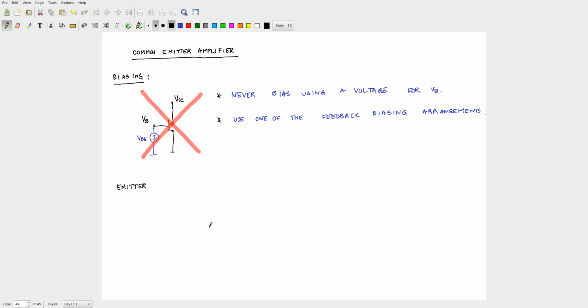So, can you quickly tell me how this may look? I have my BJT here. What should I put here? I should put a current source. Very good. And then here I can have some kind of load for fun, it does not really matter, alright, and that is VCC. And what about the base voltage? What did we do for the MOS in order to get the gate voltage? We had an RA-RB.